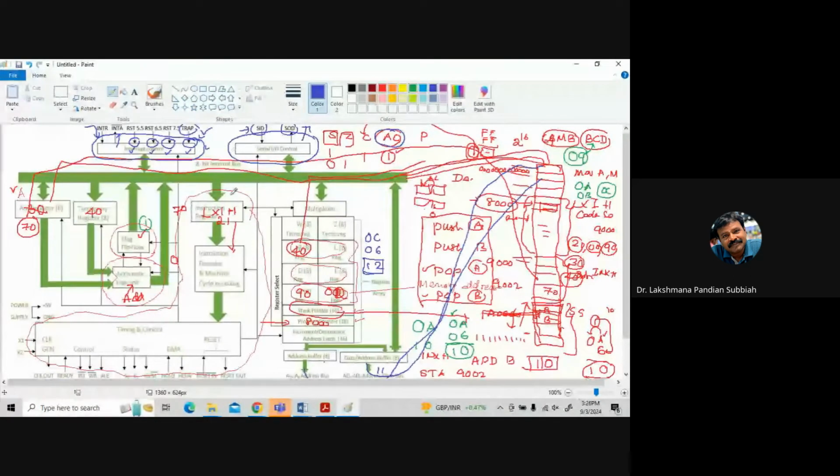The interrupt controller can interrupt while some program is executing. It will service that interrupt and return back to your original program, like a function call in C. The interrupt can occur anywhere within the program. So this is a program, and if an interrupt occurs at that time, it will stop the execution at that point and give the service for that interrupt.